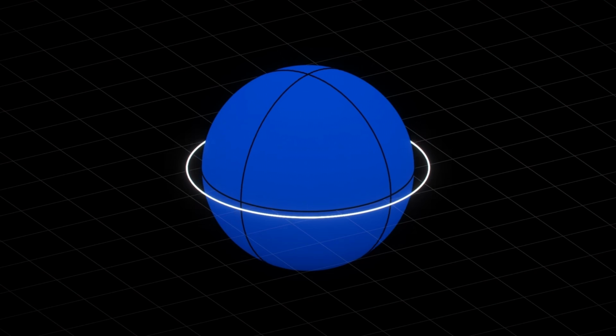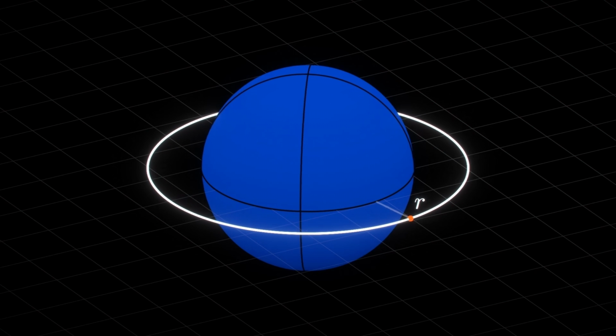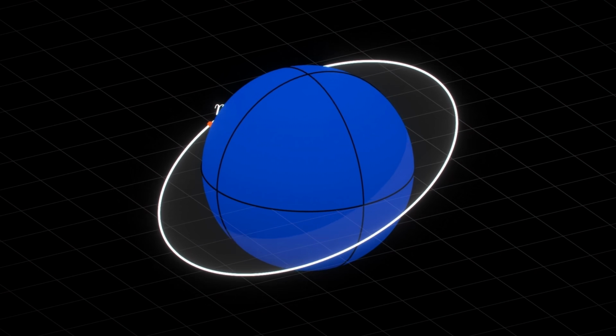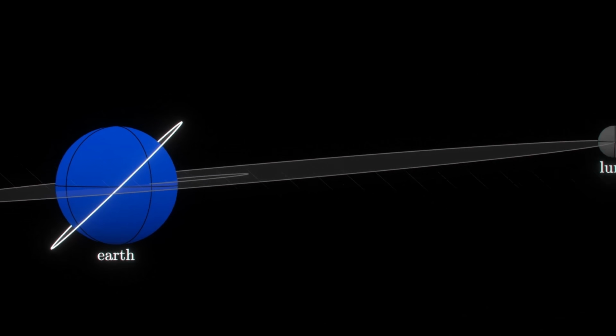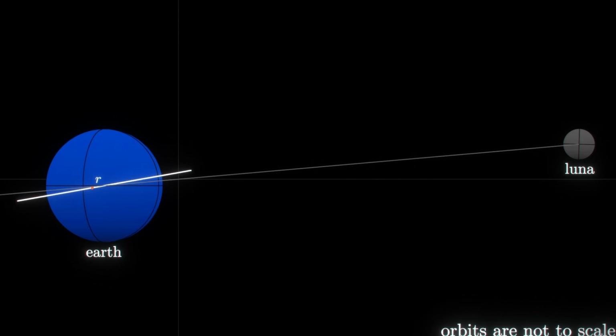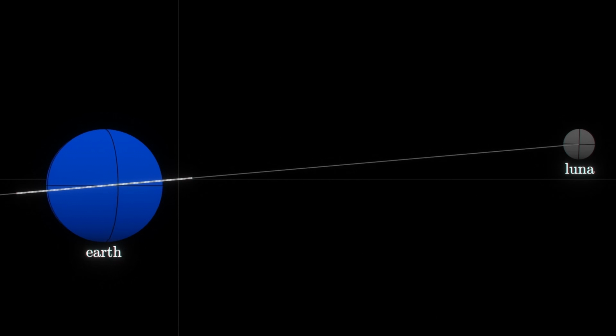But altitude is only one scalar in the orbit. Inclination matters just as much because it sets the orbital plane, and changing orbital planes is extremely expensive in terms of delta V. It also dictates the Earth launch geometry and therefore the launch period. The first and most ideal choice would be a station in the lunar orbital plane due to the lack of required inclination changes.